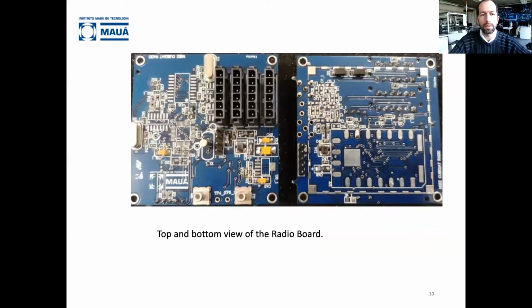Well, this is another radio board. This radio board has a particular schematic because we have a DTMF, like a telephone, an old telephone. You can press the keys and listen to 2 tones, DTMF, and this board sends messages to our base station via 144 megahertz, with modulation in DTMF. Okay.